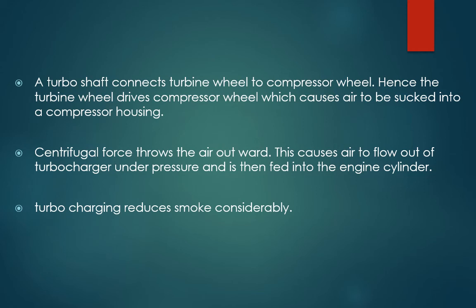So in order to trade off the reduction in the density of the air, we will remove the heat from the air before it goes to the engine. That's why you find an intercooler in between them, right? Otherwise the increase in the density may not be at the level that we want. If the increase in density is not significant, the volumetric efficiency would be reduced, right? So what to do about that? If the mass of air for the same displacement volume is more, that could increase the volumetric efficiency of the engine. That is why the intercooler is utilized: to cool the air, increase its density, and pass it to the engine, right?